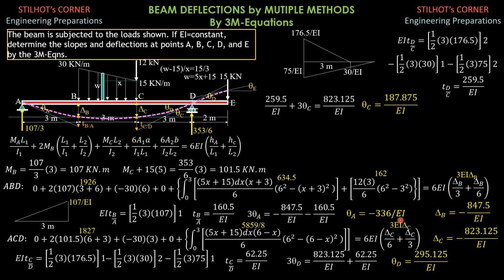So next, we consider the portion. There is no delta B here, but we can compute delta B by drawing the tangent at B. Then we may compute the deviation of A relative to the tangent at B. Then from there, we compare the deviation of A relative to the tangent at B against delta B, so that we can set up the formula for the slope at B.